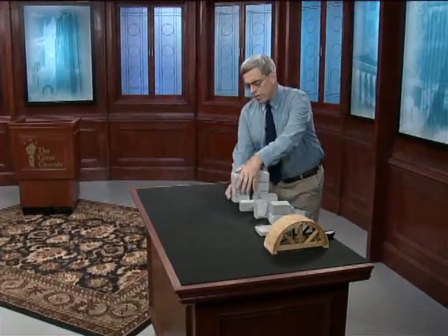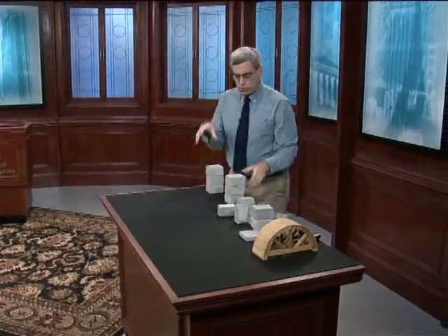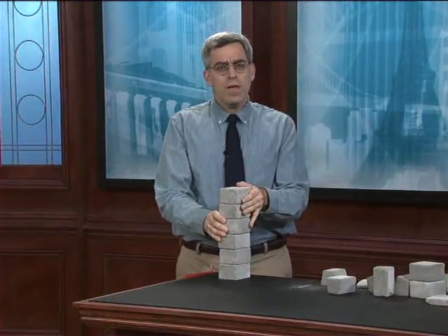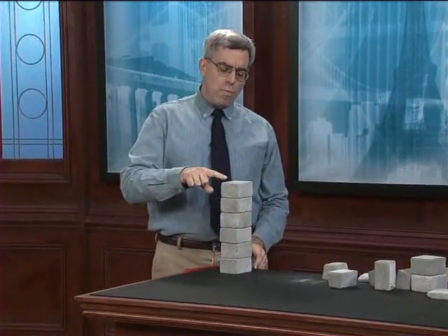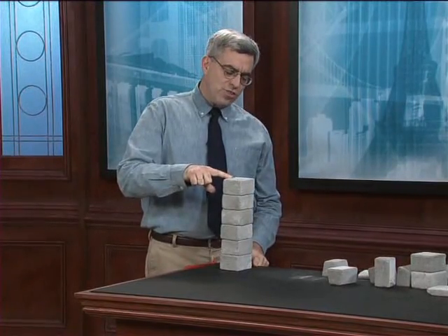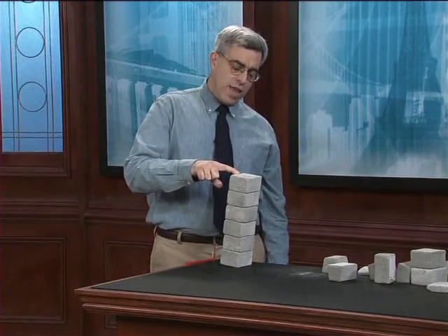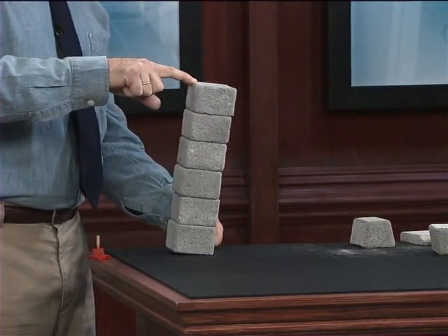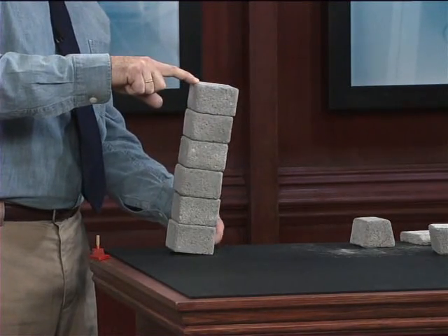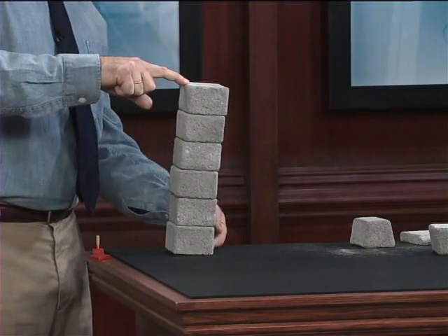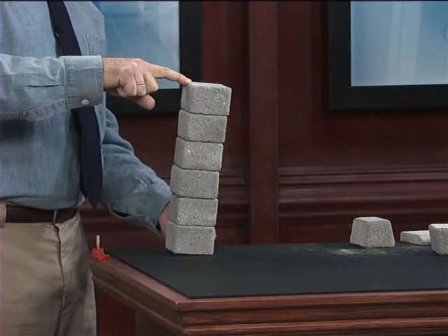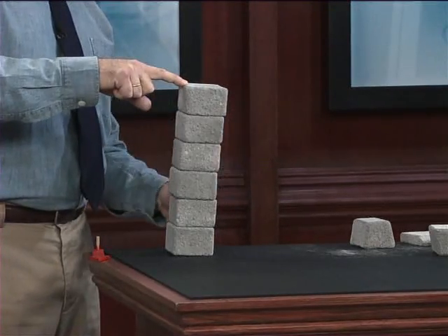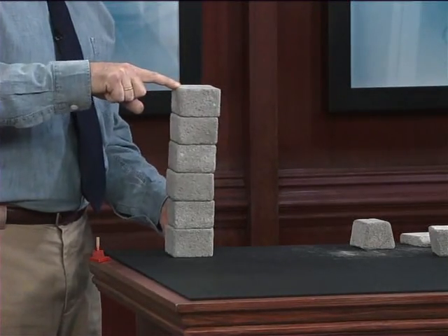Let's actually reconstruct one of those columns. Just use a stack of our stone blocks here. And note that we're modeling the condition of the column at the instant before it overturns. And notice that at that instant, just before it overturns, the entire weight of the column is balanced on this corner, the one that's on the bottom side and opposite the direction of the application of the load. And that's why both the vertical and horizontal reaction are concentrated at that point.